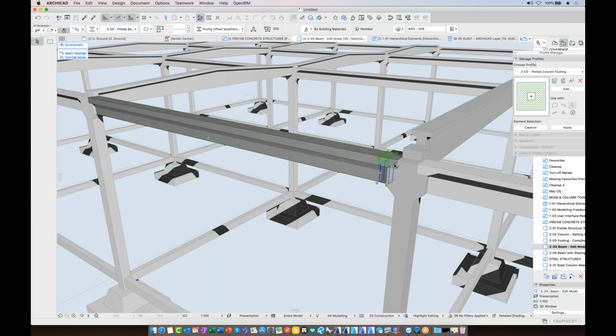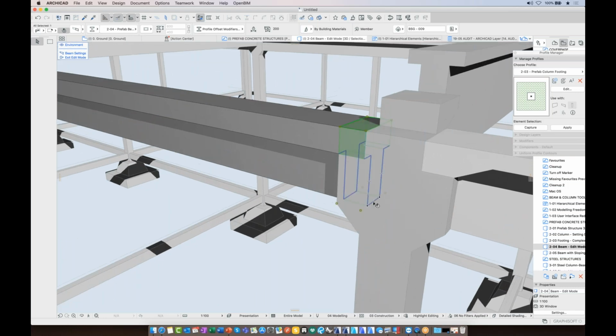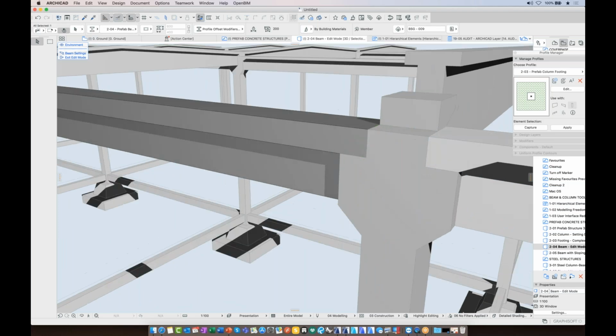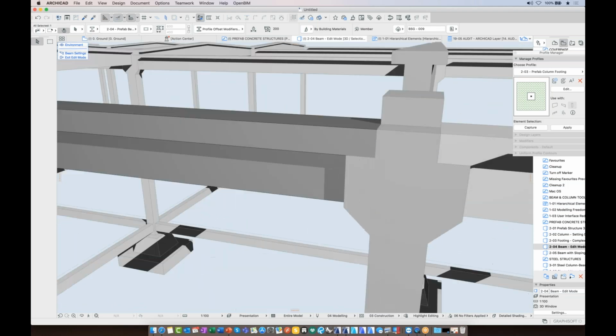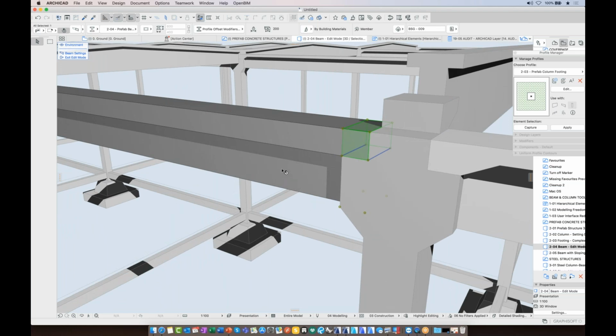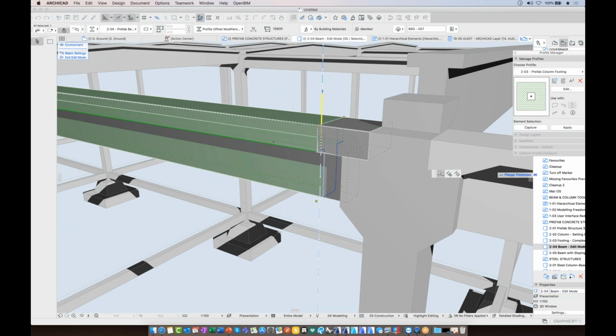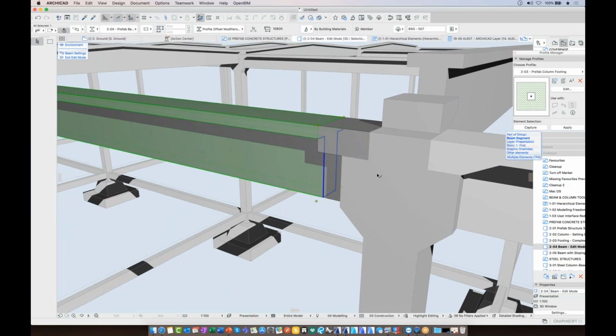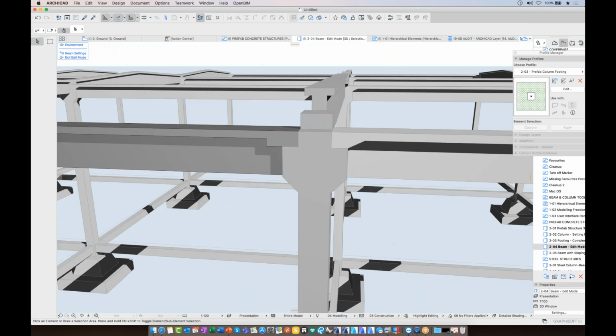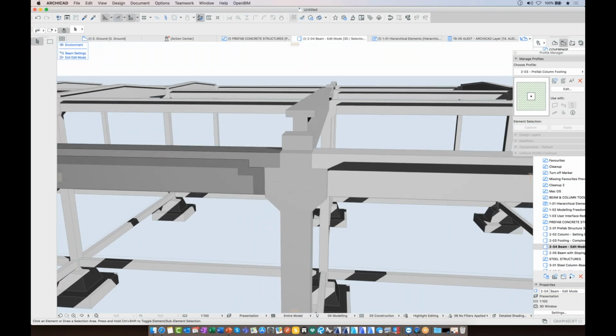In this edit mode, as you saw previously with the footing, I can select the individual segments of this beam. And thanks to profile modifiers that were introduced last year, we can start to offset these parts. So maybe in this first instance, we'll just offset that lower section of the beam. Then I'll switch to the middle section and offset this up, like so.